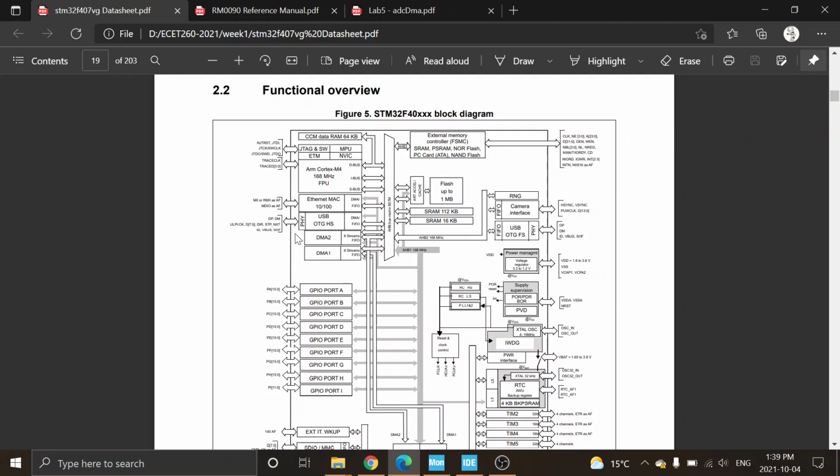And not only that, but it could say, well, you might want to move something from a GPIO port into maybe a USB, and maybe it won't involve what another one will do, and it can use another set of buses that aren't being used. And this arbiter takes all the different needs and figures out who gets the bus and who has to wait. Okay, there's a lot of complexity there. It's done for you. And so what I need to do is have a look at using DMA1 and DMA2 and how I'm going to use that.